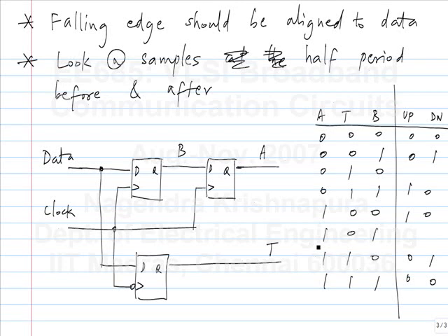You can either leave it as don't care, but typically what you do is you just push the VCO to one side. So let's say you just make up equal to 0 and down equal to 1. It will steer the VCO to one definite side instead of just hanging there. So it turns out to be better in practice than leaving it at 0.